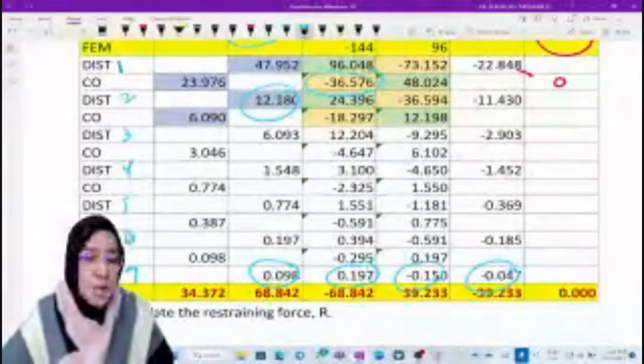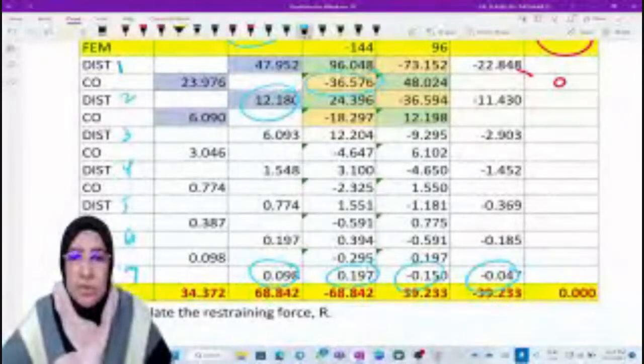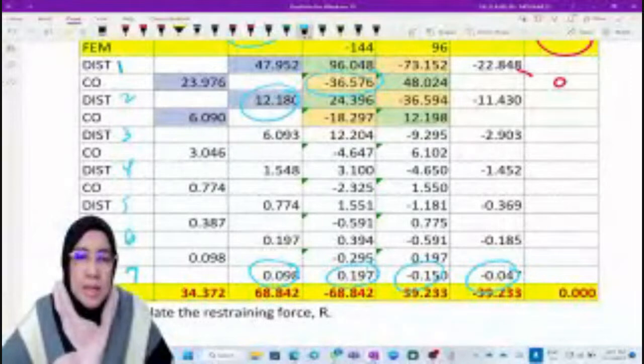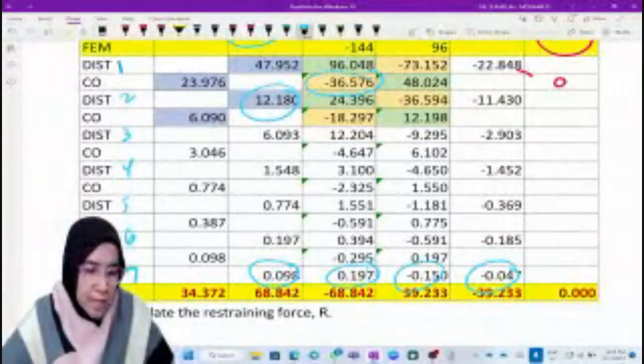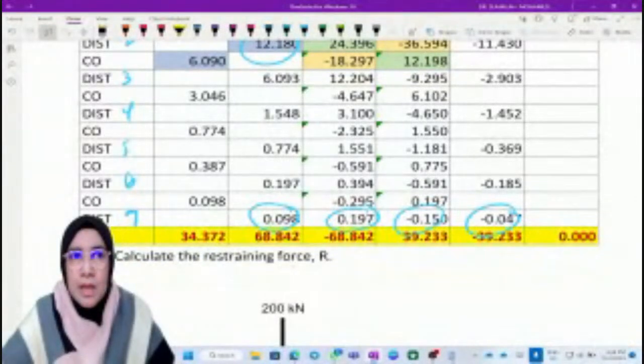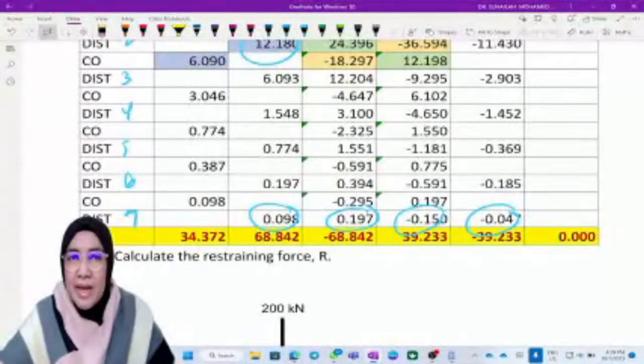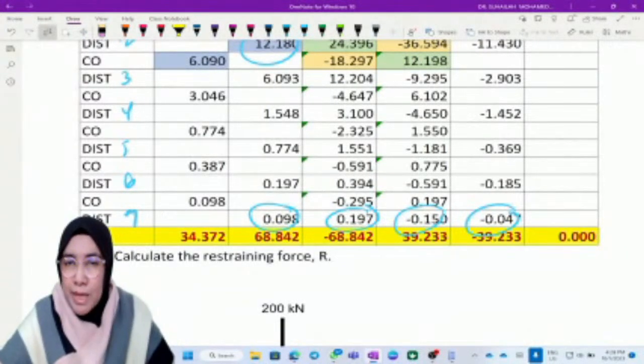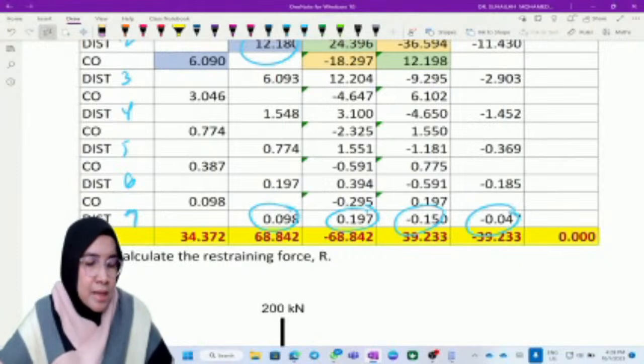Please also refer to other videos in my YouTube channel. So we get M naught. This is a non-sway frame, a fully restrained frame where we calculate FEM due to external loading only. We have removed delta from the system. So we have an extra step compared to the beam, under step 2C.